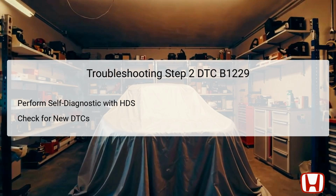Following the initial step, the next procedure involves performing a self-diagnostic function using the HDS or the climate control unit directly. The self-diagnostic check will run through various tests to assess the functionality of the sunlight sensor circuit and related components. Following these tests, you must check for any new diagnostic trouble codes that may have emerged. It is essential to note whether DTC B1229 still appears. If it reappears, it indicates that the issue was not a temporary glitch and further investigation is necessary.